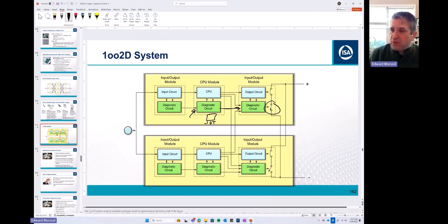So you see the difference between safety configured and certified. When you buy that SIL 3 certified PLC from a reputable manufacturer, the diagnostic of detecting a stuck program is sitting on the circuit board of what you bought. You don't have to do any programming. You don't have to do any purchasing of equipment. You don't need to worry about trying to figure out how you're going to de-energize to the field. The equipment vendor installed all that and programmed all that, and it's sitting on the PLC you bought. You couldn't turn it off if you wanted to.